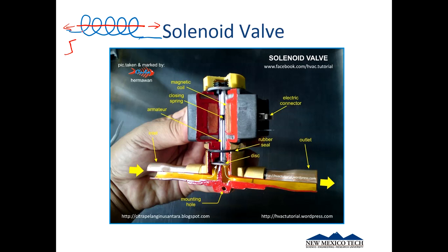We get that, it changes the current quickly, and that forces this metal rod out. And a really simplified version would be to have a gear on the end of this. That's a really bad gear, but there it is. And that gear engages with the ring gear that starts your engine. That's why when you turn the car to start, once the engine starts, you let go of the key and it springs back, and this retracts and isn't just sitting there trying to grind against that gear.